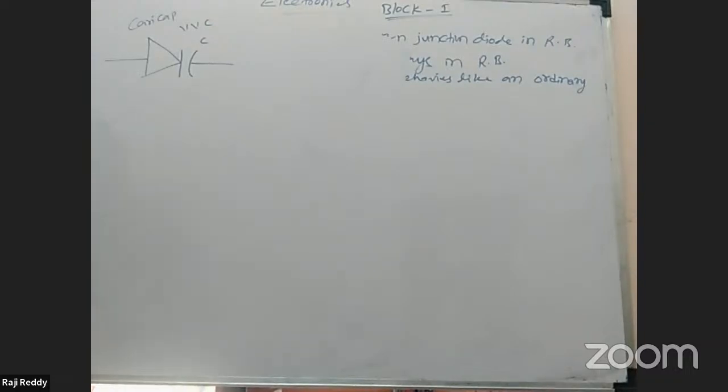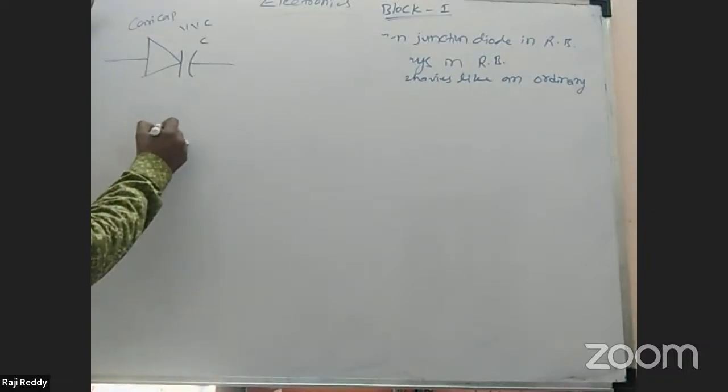The explanation part: it exists at the PN junction when the element is reverse biased. Under reverse bias condition, it was established that there is a region of uncovered charge on either side of the depletion layer junction.